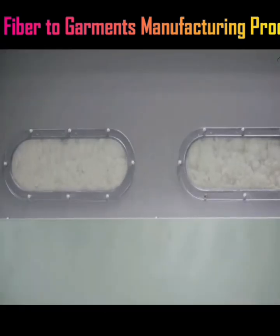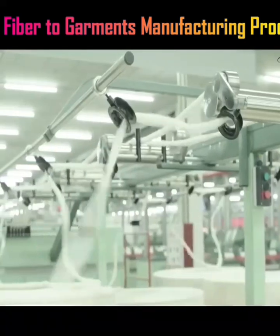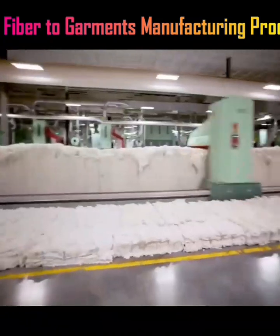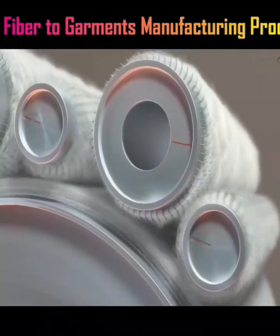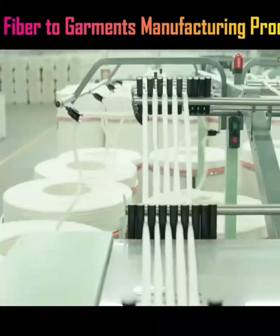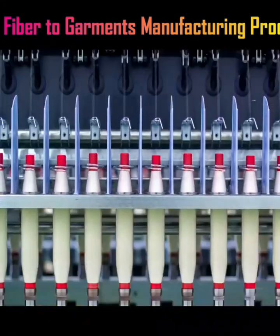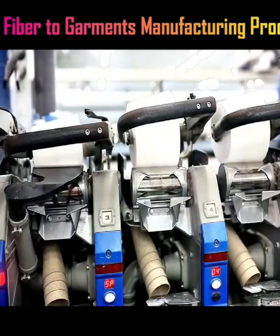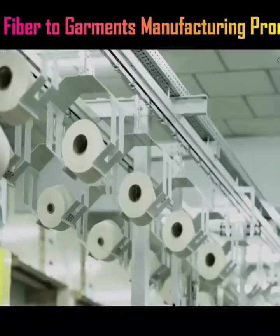bale opener machine. Then the process is followed by a series of continuous operations such as blending, mixing, carding, drawing, roving, and spinning. And finally, we get the cones of yarn, which are used to make fabric.